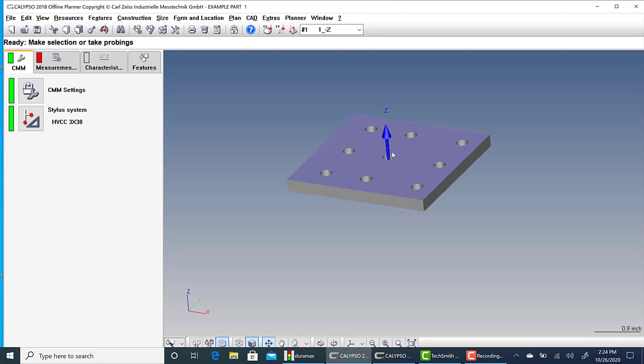The CMM is a little different, where you bring the software or the program to the part, and the machine will move based on that alignment. So you don't need to have real solid setups here as far as indicating the part in and whatnot. The machine will do that. Okay, now you don't want to be off by 1/8 of an inch, but if this part is kicked,